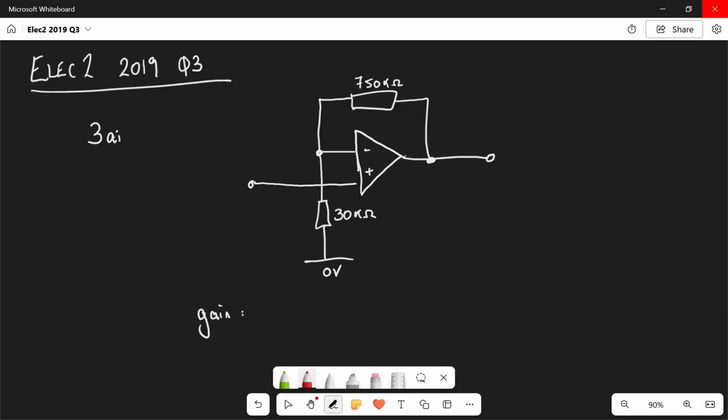Now, for part A, that diagram is a classic diagram, normally shown where one amplifier is insufficient for the gain needs, but what we need to realize is that the bandwidth of the individual amplifiers is maintained through the system. The circuit diagram for each is given below. Well, we've got a picture of that particular circuit diagram, and what we need to realize when looking at this is that this is a non-inverting amplifier.